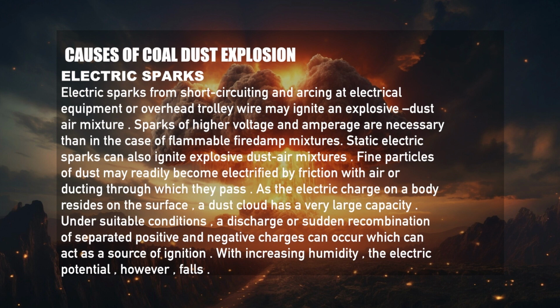Static electric sparks from batteries can also ignite an explosive dust air mixture. Fine particles of dust may readily become electrified by friction with air or the ducting through which they pass. As the electric charge on a body resides on the surface, a dust cloud has a very large capacity.